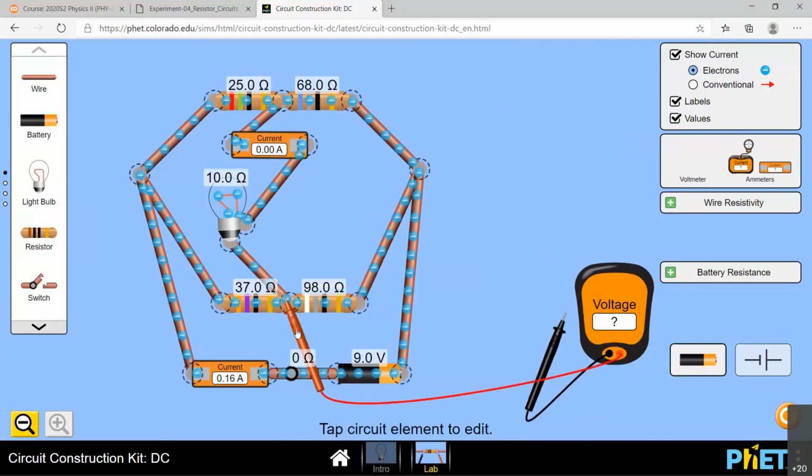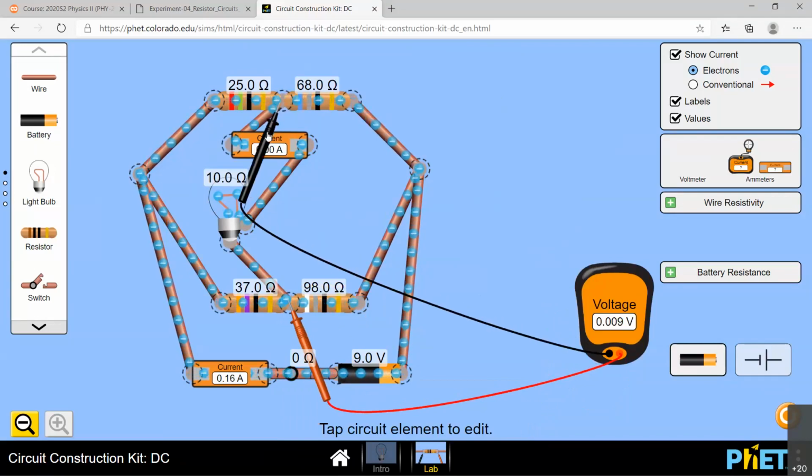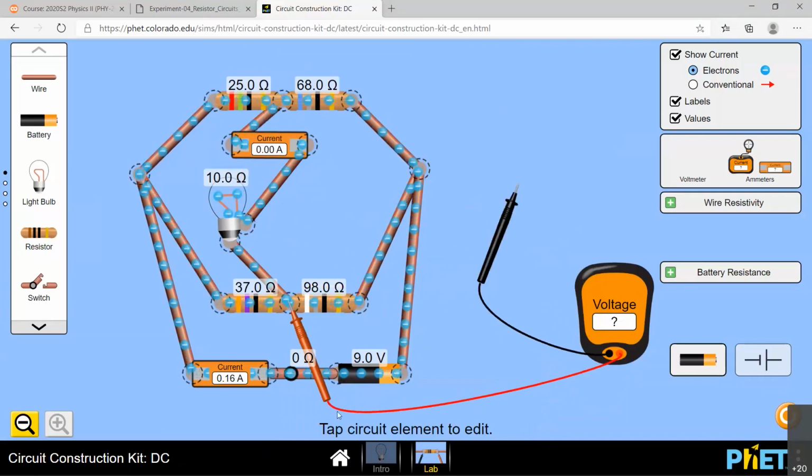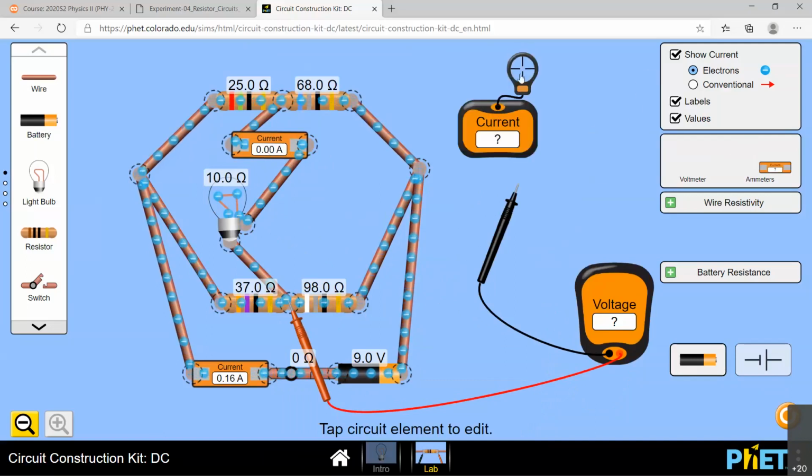Then let's take a look at the voltage across that. Still you have a small voltage. See the difference right now? That's the problem. If you use the ammeter there, you will still get a large error, right? The calculated value is 100, remember? But now I am getting current 0 at 98, which means our ammeter is not sensitive enough. So that's the problem. Which means using the ammeter to measure that will not be a good idea.